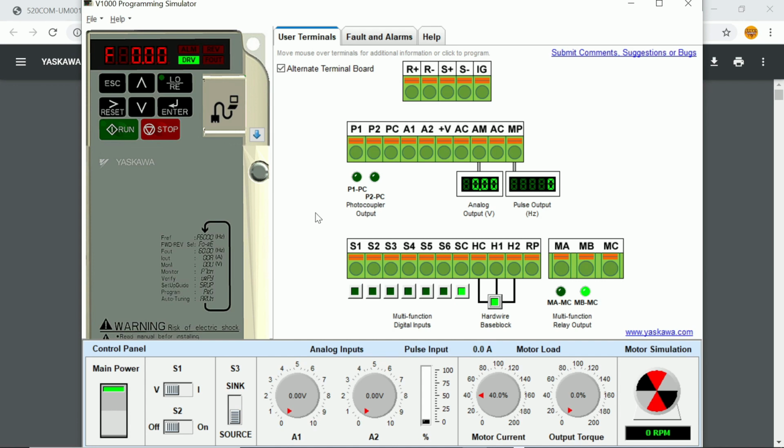Okay. So if I do this again and I connect it again, it clears out the alarm. Now there's certain situations where the alarm is wiped off with our reset button. The failure or the fault is exactly the same thing, but remember, there's something that's happening, and it's going to continue happening as long as there's still that fault.